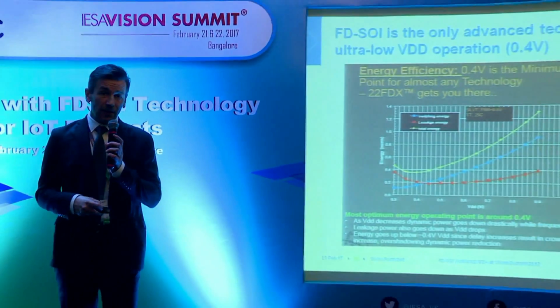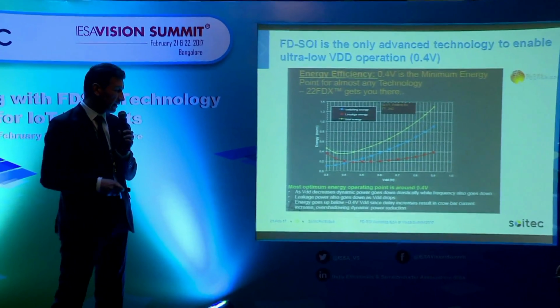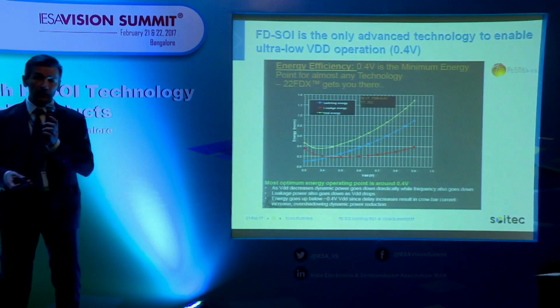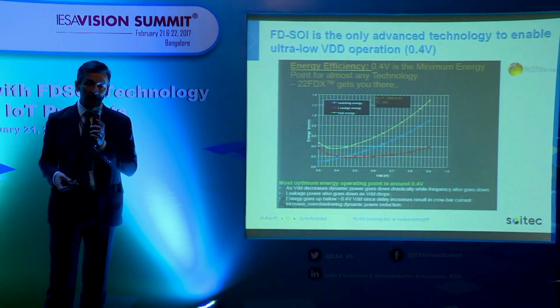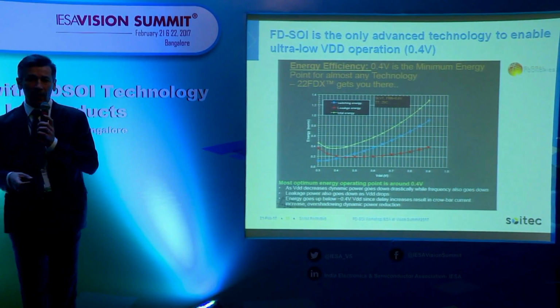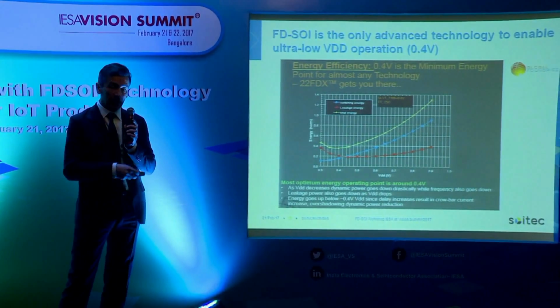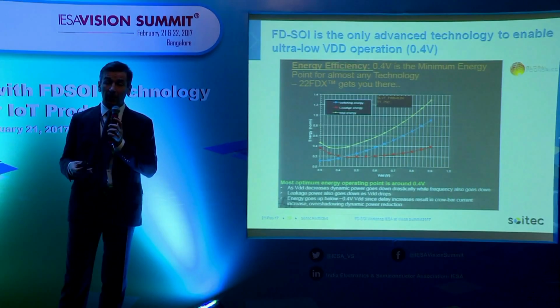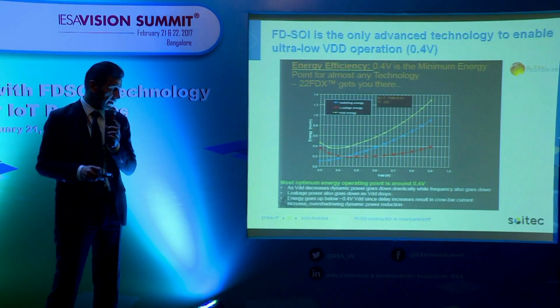So this is another amazing point about FDSOI: performance at 0.4 volt. And here you have the data from Global Foundries. Now they are demonstrating that the first chips are already reaching this type of working point today on the market. So 0.4 volt, again, for IoT mobile applications, is a very unique value you can get.